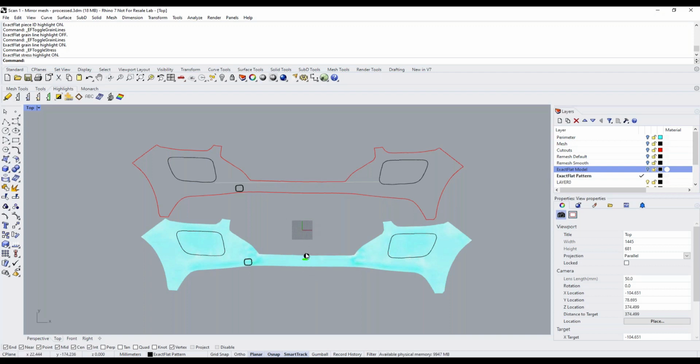Transverse strain is the opposite, perpendicular, so I didn't do any transverse strain, so we didn't compress it in that orientation whatsoever. So it's just an easy way for you to apply a strain to your part, such that you'd have to essentially stretch your part by 2.5% to get it to fit the surface area of your original 3D model.